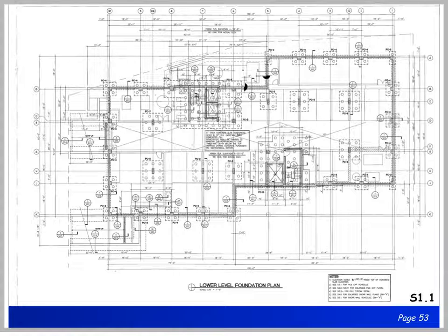The first plan in a structural set will be the foundation plan. Like floor plans, the foundation plan is showing the layout of the lowest level portion of the structure, usually the same as the lowest level floor of the architecturals. There's a lot of information and section cuts directing the builder to additional information. Note, the column line grid system is the same as the architecturals.